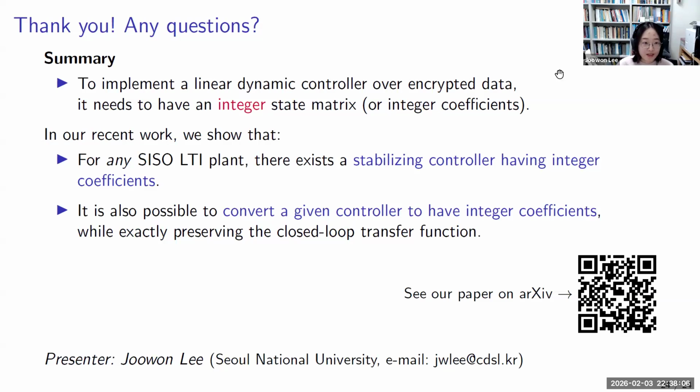So, yes, this is the end of my talk. To summarize, I have shown that to implement a linear dynamic controller over encrypted data, the controller needs to have an integer state matrix, or for single-input, single-output systems, just have integer coefficients. In our recent work, we have shown that for any single-input, single-output LTI plant, there exists a controller having integer coefficients that stabilizes the given plant.